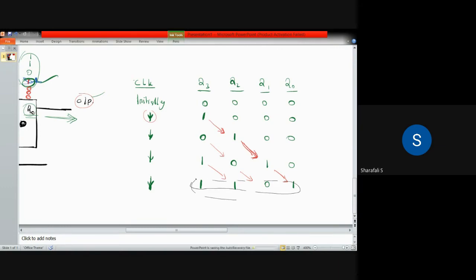But in this particular configuration, which means serial input and serial output, we have a problem: we will not get output directly from Q3, Q2, Q1, Q0, because we are taking the outputs serially. So we can take the output from Q0 only. But in that case, we are having 4 zeros here initially, and only then this one. So that is not the output that we require, right? Because we are not giving the data 0 0 0 0 1. That is not the data that we have provided.